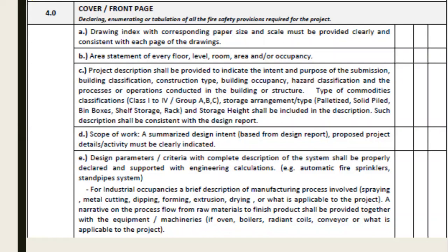Second one is the cover sheet. You still remember the sequence we have? Cover sheet, the layout plan, the sectional elevation, the miscellaneous details and the risers. This is the sequence of submission. The cover sheet, or the front sheet, drawing index with corresponding paper size and the scales to be provided clearly within each page of the drawing.